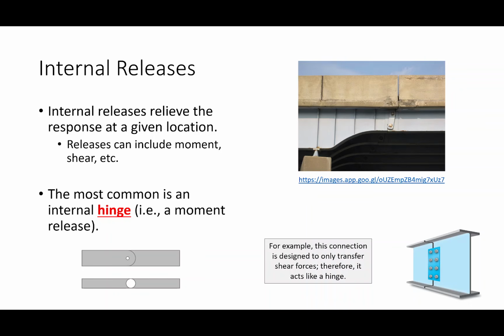But these pin and hanger connections resulted in a structure that adhered to the analysis simplifications that we made during the analysis phase. So if we assumed this to be a hinge, this actually behaved like one. And one of the reasons that we placed these hinges inside the structures is to make them solvable by hand, and that will become clear pretty soon when we start classifying structures. So if we wanted, a more modern real world example of a hinge might be something like this.